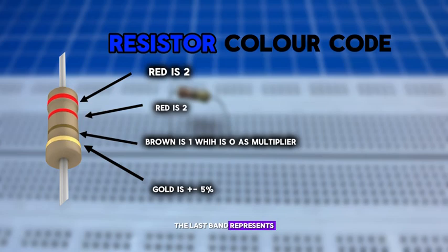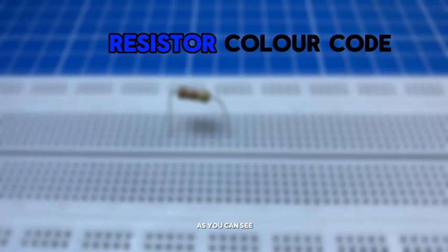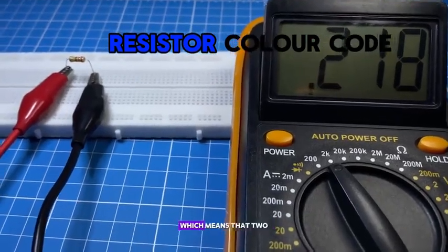The last band represents the tolerance level, and the tolerance level of the resistor is plus or minus 5% tolerance. So in this case, the resistance value of this resistor is 220 ohms, with plus or minus 5% tolerance, or 0.22 kilo ohms. As you can see on the multimeter, it is showing 218 ohms, which means that 2 ohms is the 5%.